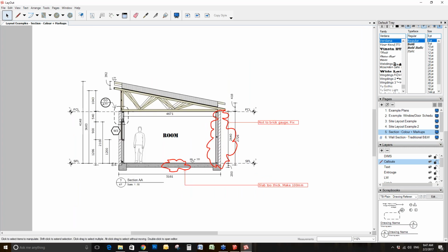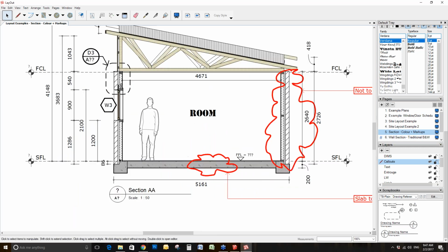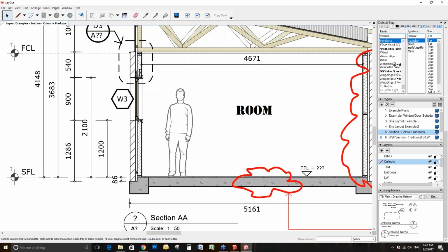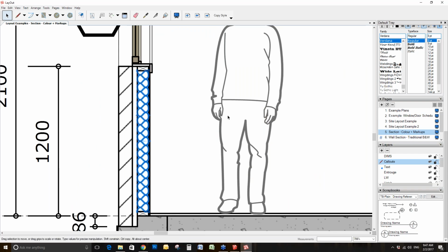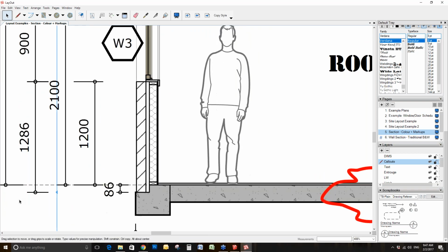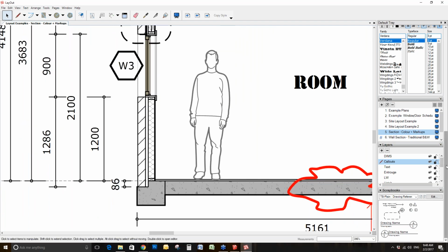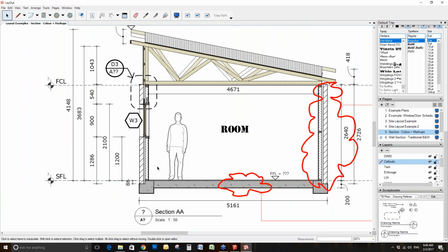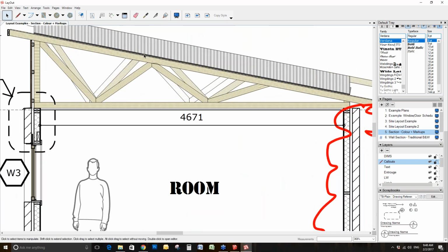Sections and markups. PlusSpec gives you the ability, obviously, as I said, to capture the different hatching, but it's very easy for you to go in and to essentially bring in any kind of profile or hatching that you want to use. So if we don't have it, or if it's not available, or if it doesn't work parametrically, simply go in and create a hatching layer and create the one that you want to use. This is a reference of the color and texture.